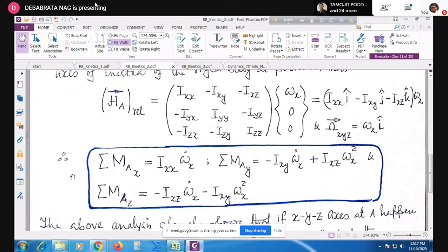But you should not forget that above and all to this equation, you have Newton's generalized equation, which needs to be written, which takes care of all the forces which are acting on the body and which should be equated with the mass of the body times acceleration of the center of mass, as shown in the free body diagram. So this Euler's equations as well as Newton's second law, the coupling of these two equations need to be applied.